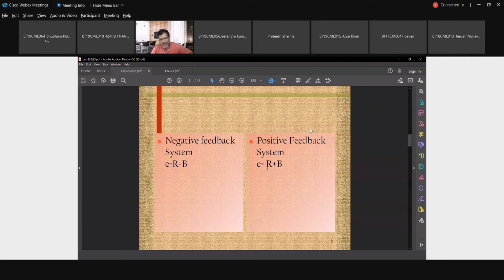समझा? ये समझा गया. But these are the some terms which are needed, you should know कि भाई नेगेटिव फीडबैक क्या होता है. It's the difference between the set point and the measured variable. B is a measured variable. Okay, and positive feedback is something we are adding the set point with the measured variable, so always it will rise, the error will always increase. And error increase होना है ना, क्या है, सिस्टम अनस्टेबल है. सबसे पहली बात है ना, हमें एरर बढ़ने नहीं देना है, कम करना है.